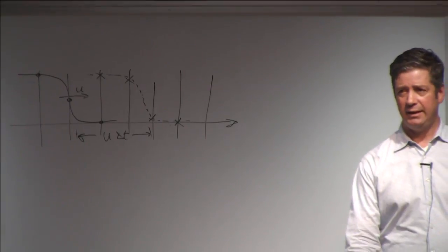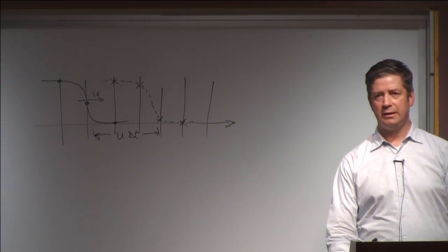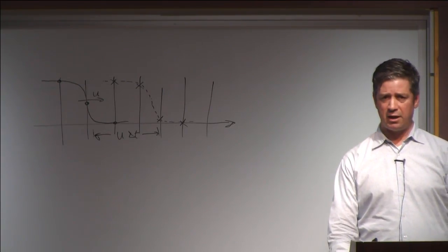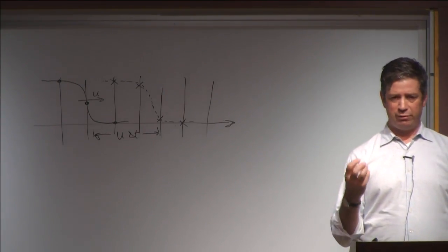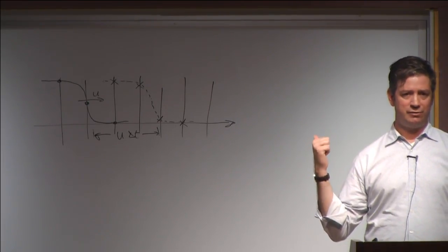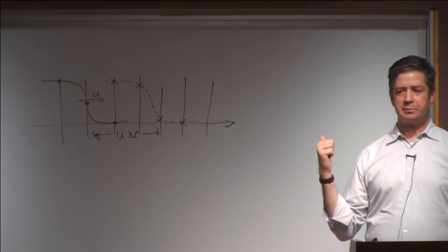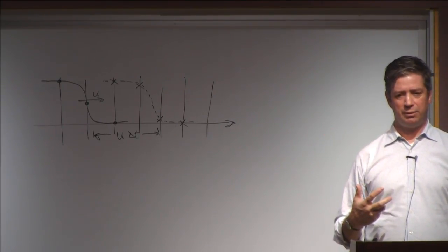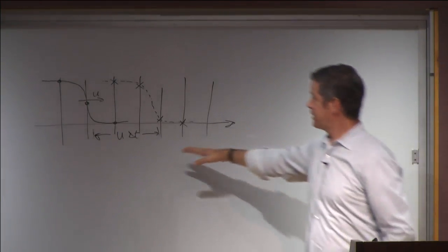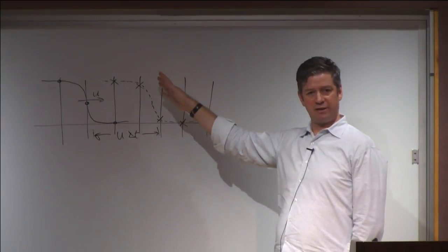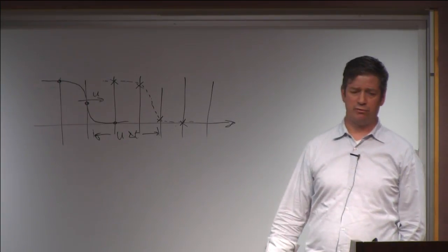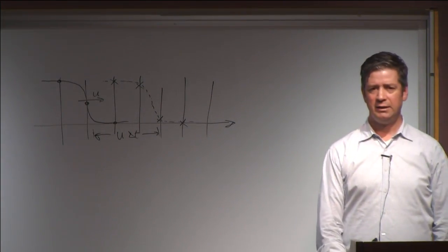Usually, it's a good bet when you have advection diffusion, or when you have, for example, a viscous term in the Navier-Stokes equations, because as you refine that viscous term, it gets more and more stiff, and you need something more and more like a diffusion solver for it. If you're just doing pure hyperbolic problems, multigrid might be a good preconditioner to get a first guess, and then you could do some kind of Newton or point relaxation scheme on the finest grid. But in general, you avoid purely hyperbolic problems with multigrid.